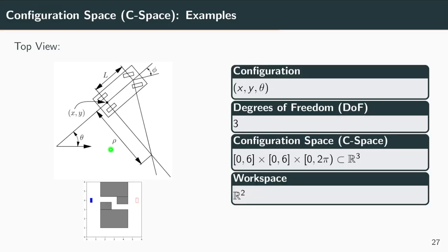So maybe for degrees of freedom, what's important, there's another related term, which is controllable degrees of freedom. And what you said at the beginning was, I think, more related to that. You can only control 2 things for a car, but the degrees of freedom are still 3 things. And that means it's under-actuated, right? This car cannot freely move in the space, but it's constrained by what you can do with the wheel.